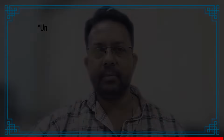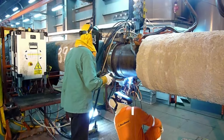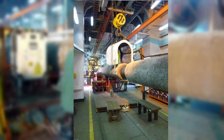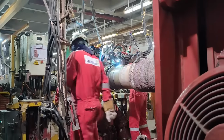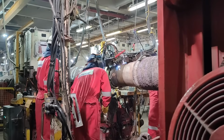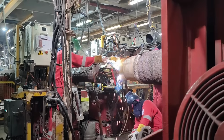Let's get back to pipelay. All pipelay barges will have a dedicated laying corridor inside the barge. This corridor is called the firing line. There are many stations along the firing line where 12-meter segments of pipes are welded, x-rayed, repaired, wrapped and foam filled. Every station plays a crucial role in joining the pipe segments, but for surveyors, station 1 or the beach stall is the most important, and you need to have an offset point for the beach stall.